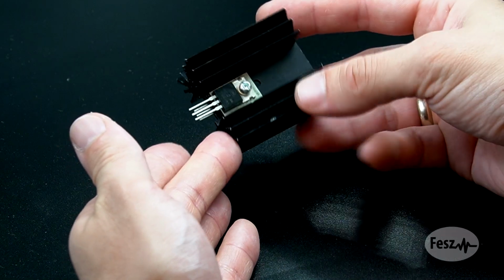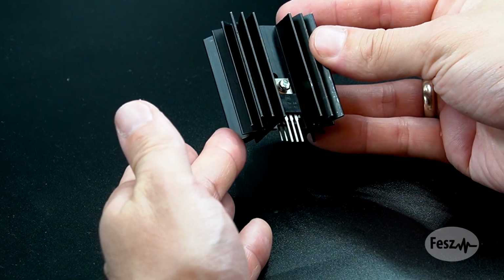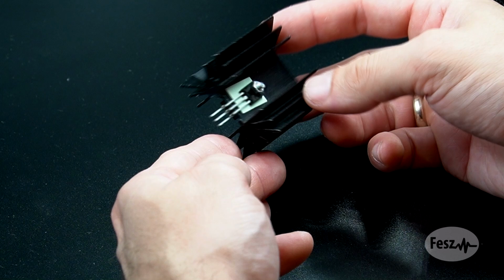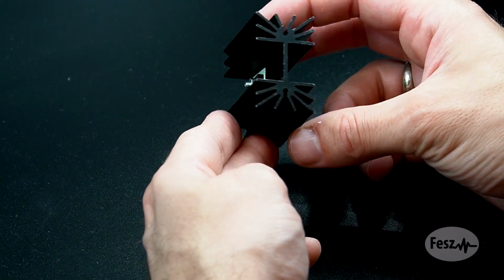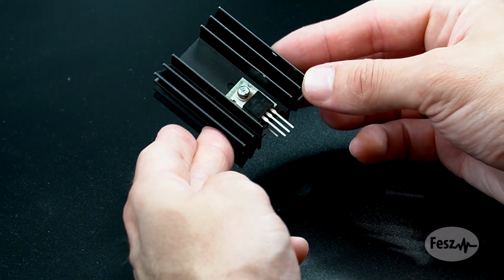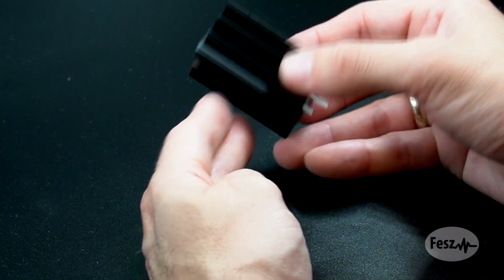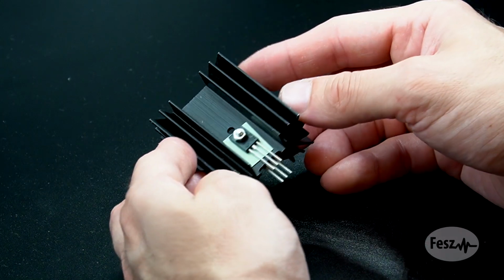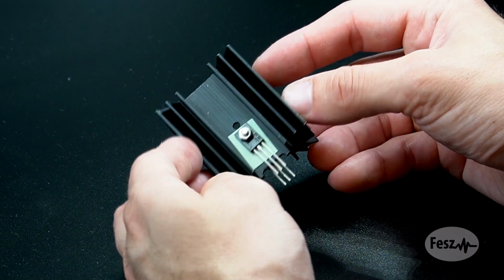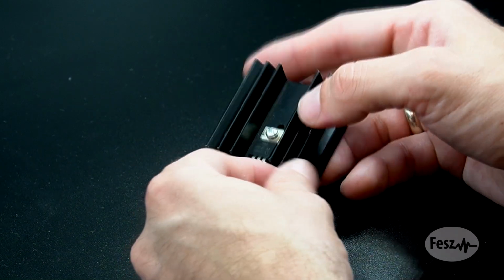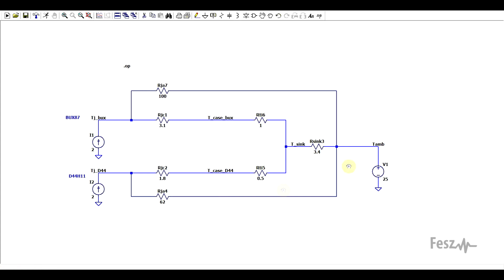So, for example, let's say we have two heat sources, two transistors, dissipating different amounts of heat, but placed on the same heatsink. While you usually want separated heatsinks, this sort of arrangement might be necessary for space saving or other reasons. So the question is, how hot does this thing get? Well, an equivalent circuit for this can be built as such.